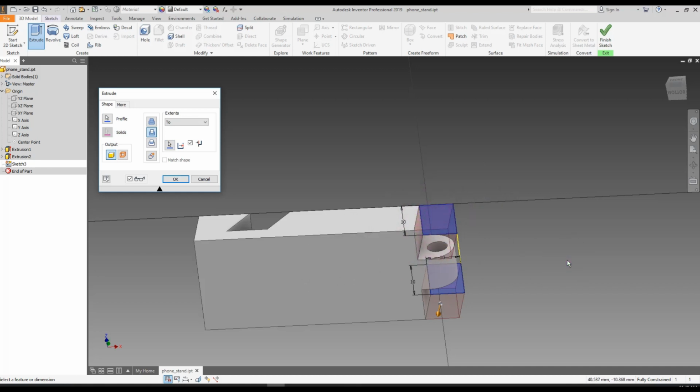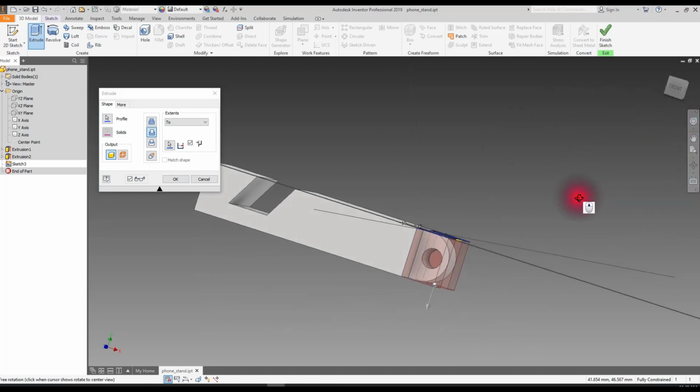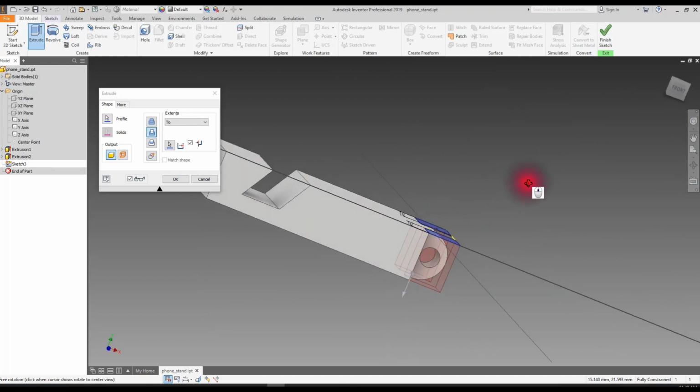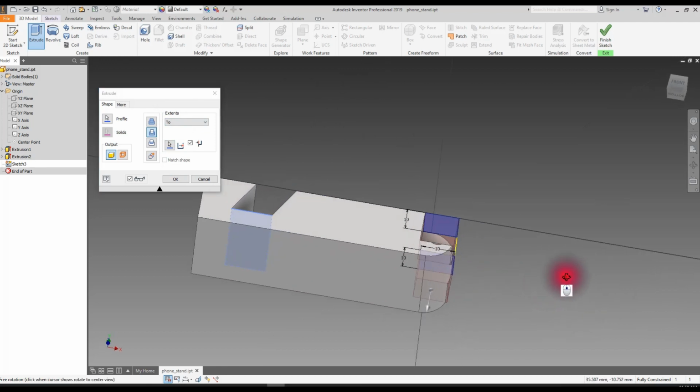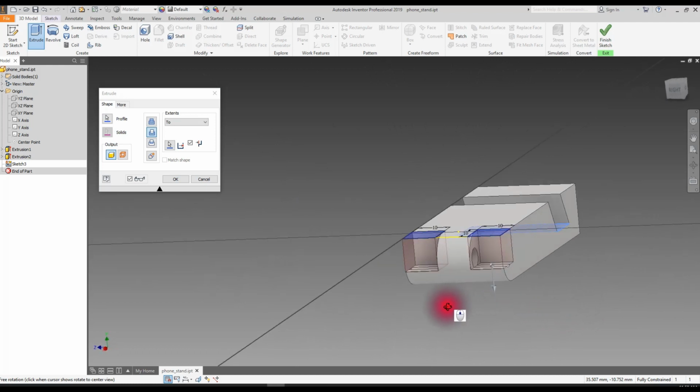Well, what's the difference with all, you might say? This is just this very same thing. Well, in this particular case it is. But let's say if you wanted this cut to be the same distance, same depth as this cut. So I'm going to choose to again, and then I'm going to click at this bottom. And now you can see this cut is the same depth as that cut. And we couldn't do this with a cut all command.